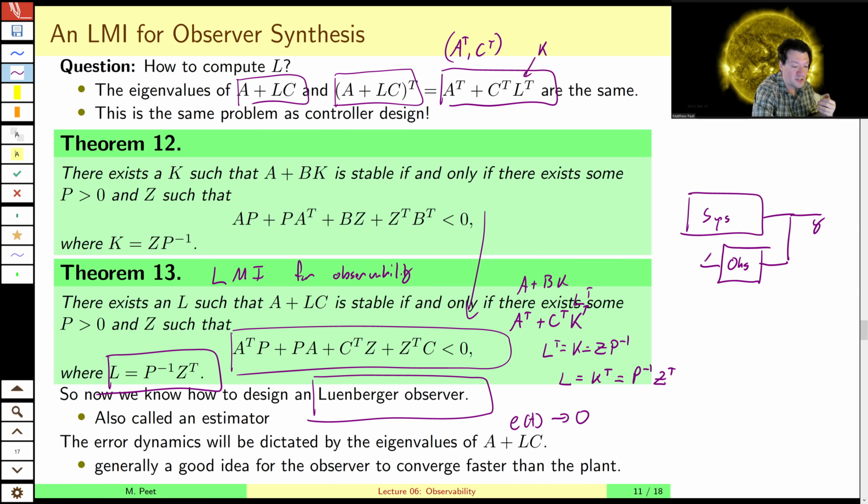So if we take our x hat here and plug it into that K to close the loop, then this actual state will go to 0, right? So taking our observer, constructing an estimate of the state, and using feedback on that estimate, we want to show that this structure for the controller, observer-based control, enforces the stability of the closed-loop system.